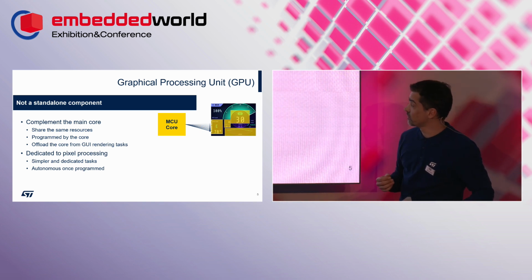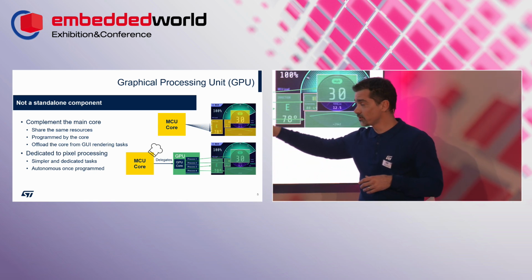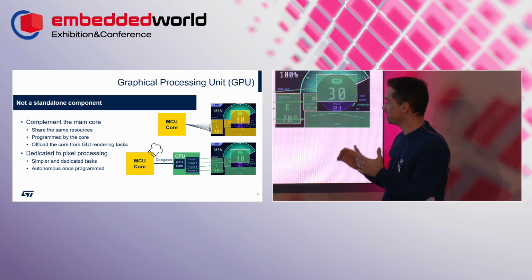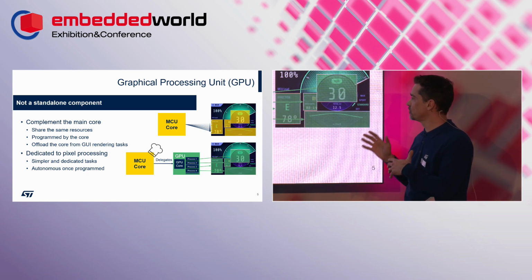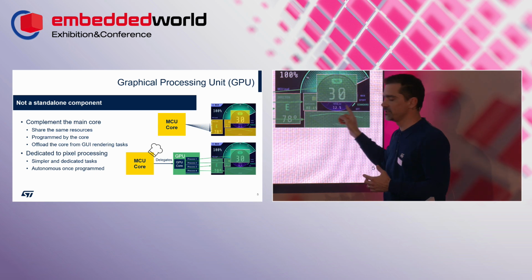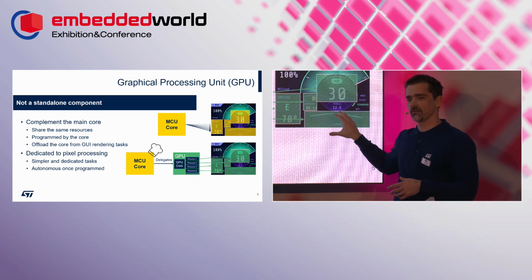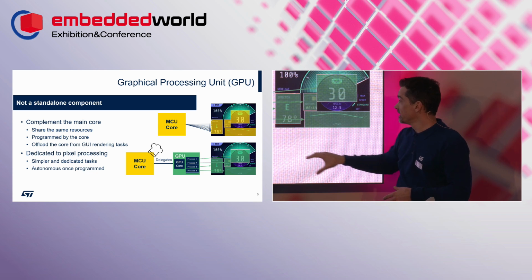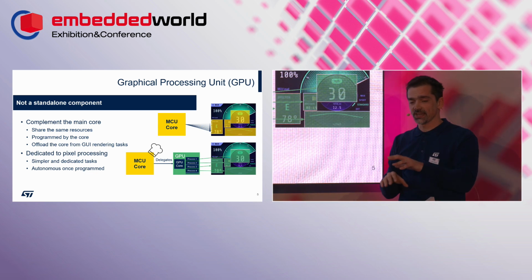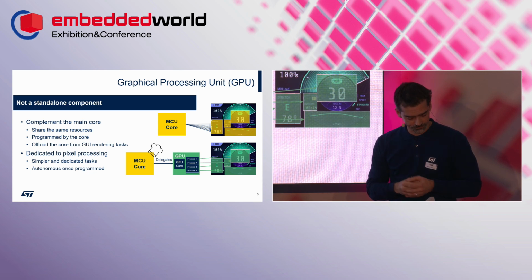If you add your kitchen assistant, then the core MCU, the Cortex, becomes the chef of the kitchen and delegates tasks to the GPU. So the Cortex will still determine which area of the display needs to be updated. But as far as the actual update of the pixels is concerned, it will be processed by the GPU, and the GPU will be in charge of doing it as efficiently as possible because its architecture is made for that.